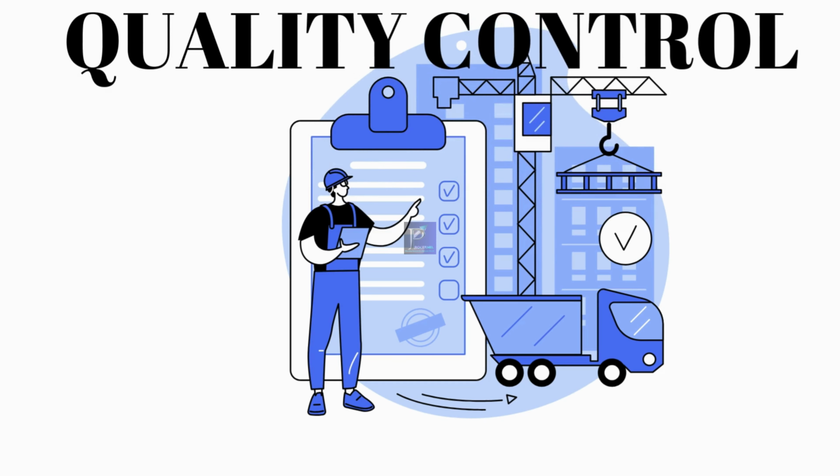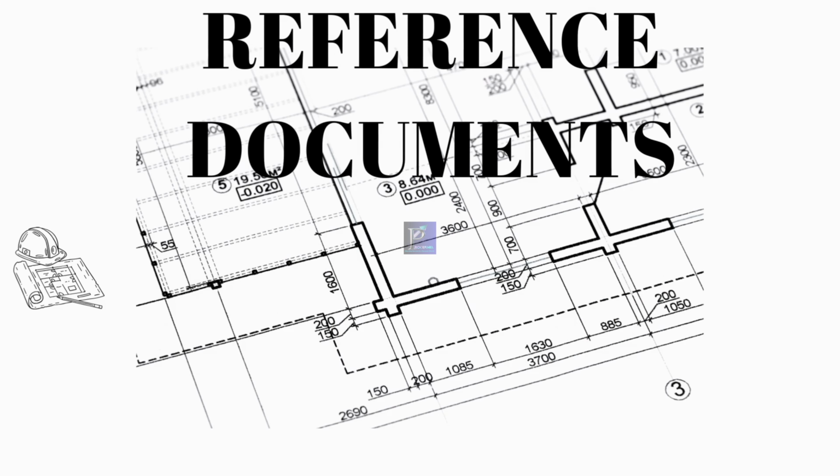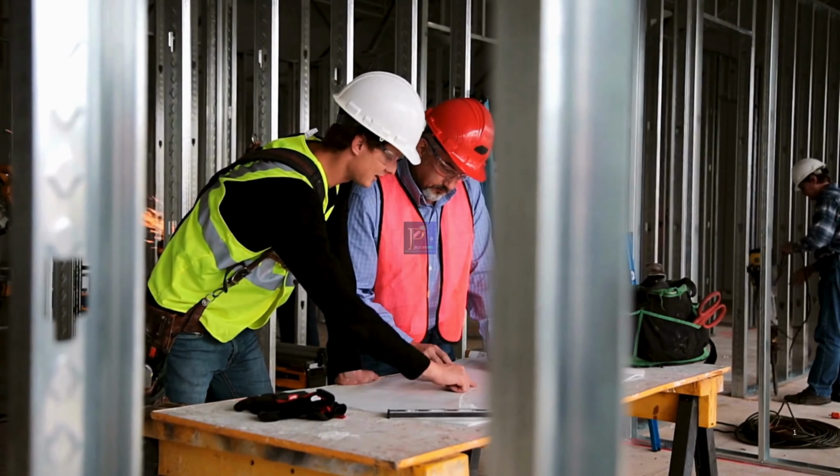Quality control, ITPs and checklist. Ensure ITPs and checklists are incorporated for quality monitoring. The hold points are properly identified in the ITP. RFIs are issued directly, so it's all there. Reference documents. List essential supporting documents such as client approved curing compound specifications, design mix details, design mix approval, approved drawings, technical specifications, and of course raw material test procedures, material requirements. All these things, everything.